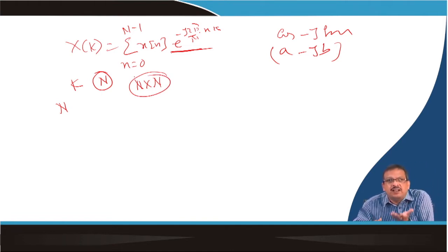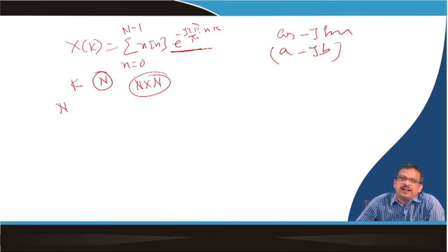So when I increase the N using zero padding in the signal, I am increasing the computational complexity, but calculation-wise there is no change. I get the frequency response of the same signal x[n], but with better frequency resolution.